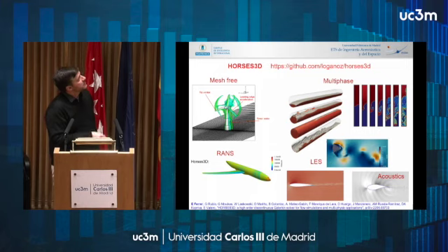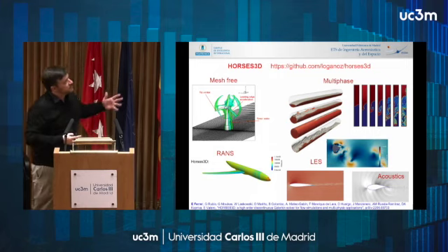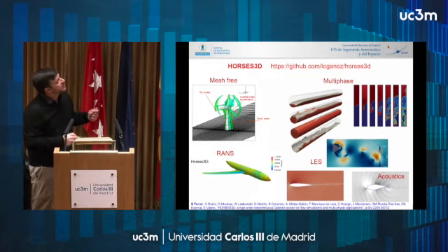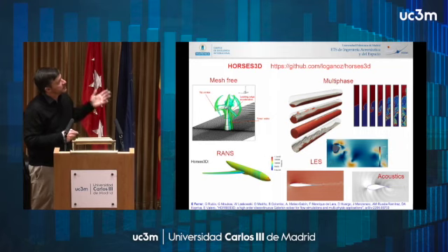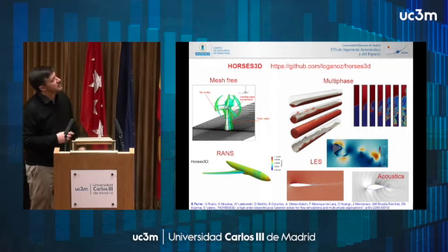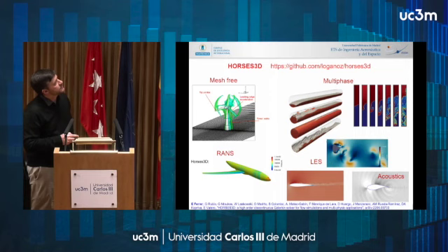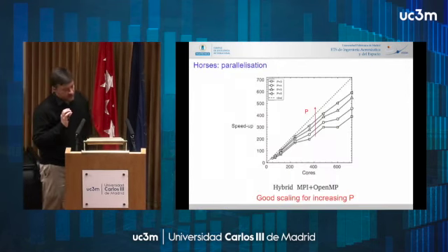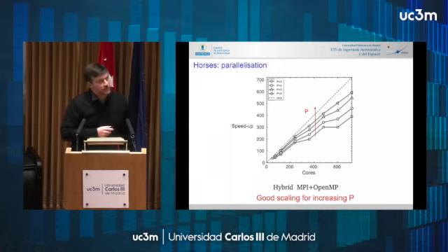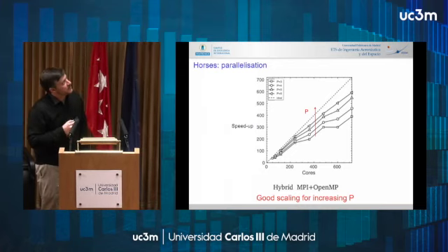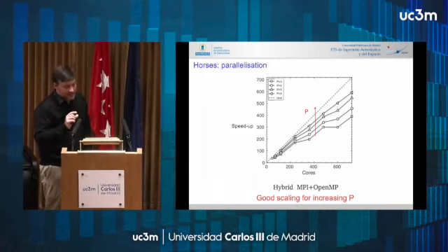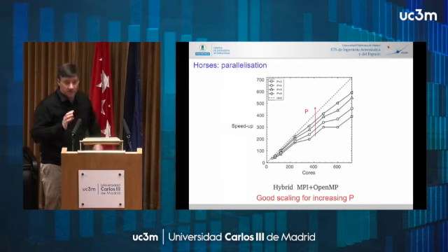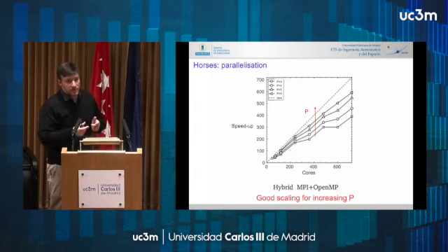Right, so this is a slide representing more or less the things that I'm going to show you today: mesh-free methods, multi-phase, RANS, LES, some acoustics a little bit, all this stuff. Before going into that, I'll show you some of the scaling of our higher order solver. The nice thing about our solver is that we can change the polynomial order, and you don't need to recompile the solver, it's just a parameter in your input file. You change the polynomial and then you're running with a higher accuracy, right?